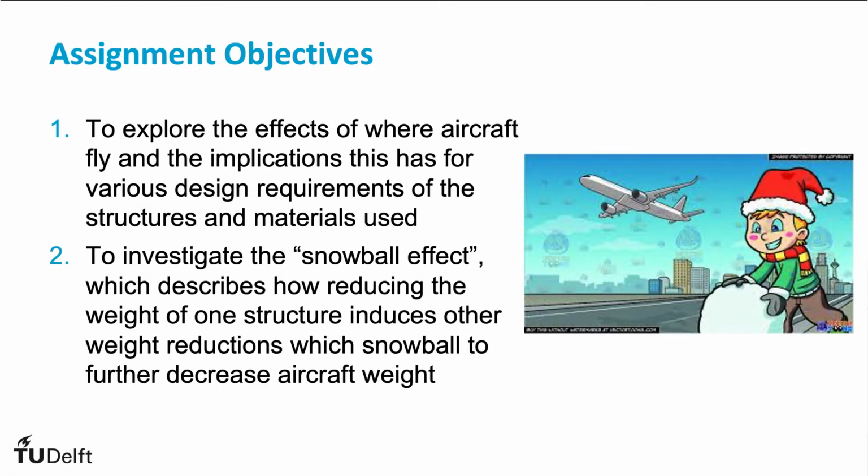As stated, we had two objectives. One, to explore the effects of where aircraft fly and the implications this has for the various design requirements of the structure and materials used. And two, to investigate the snowball effect, which describes how reducing the weight of one structure induces other weight reductions, which snowballs to further decrease aircraft weight.